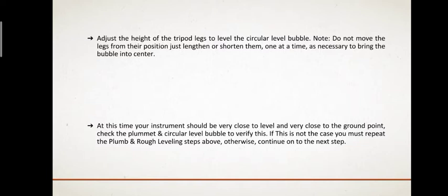We will do that permanently with the help of the foot screws, because once we bring the foot screw to the center as shown in the previous slide, you need to start turning the screws directly, either clockwise or anti-clockwise. If it is a very irregular surface, then you have to turn these foot screws a lot, right? So for easy adjustments, we do all those things.